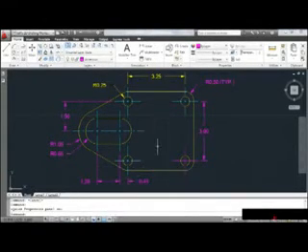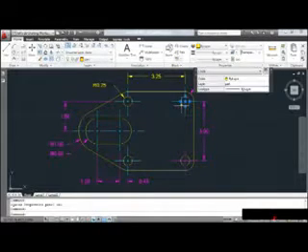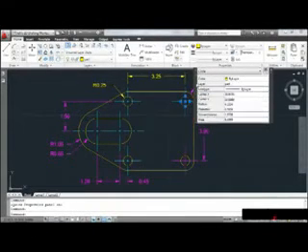And when I do, we really don't notice anything different. That is, until I select something. I'm going to select this circle, and notice that the Quick Properties tool looks very similar to the property changer. Essentially, it's the same thing. It's just a smaller collection of settings. Now, the tool is coming up in a collapsed state. If I move my cursor over the tool, it will expand and show me all of the settings.